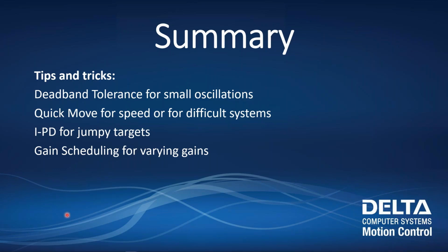Another question came in: it seems like you're always trying to make the integral term be very small. Is this always a good thing to look at and try to minimize? Yes, you probably noticed one of my favorite things to do is look at the integral gain. The integral gain is very, very good at holding final position, and it can help us track during motion, but if it winds up or winds down, that simply can cause problems, and that is often a very major issue. So yes, if you get in the habit of being able to look at that, that can certainly help. Any other questions?